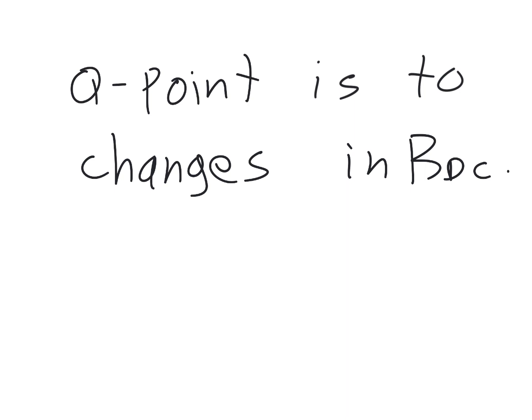I think I'm going to go back to teaching emitter bias. We taught it for many years. I've dropped it for a few years because we no longer do that in the lab. But anyway, it's an interesting circuit. It's actually technically more stable than the voltage divider.